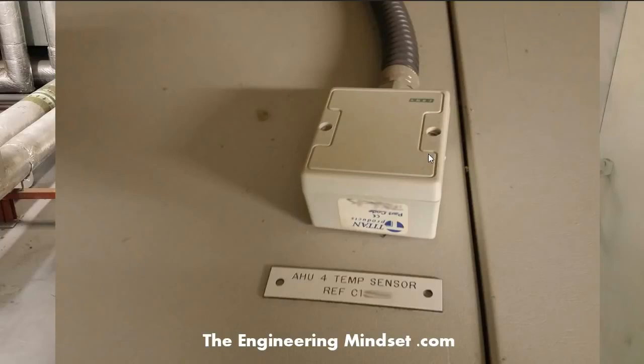So this is bolted to the side of the unit, maybe onto the top of it, and these would be various ones, and there's a rod coming inside the unit there taking measurements of the temperature of the air. And you may have noticed at the top here this tube sticking out, sticking through the top. That is your temperature sensor right there, and that's taking the measurement going onto this heating coil here, and will dictate through the controls how that should operate in response to that.